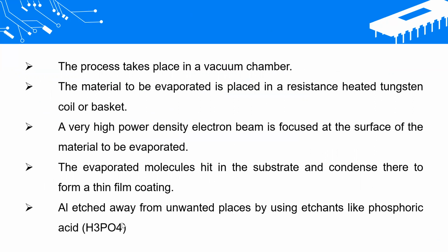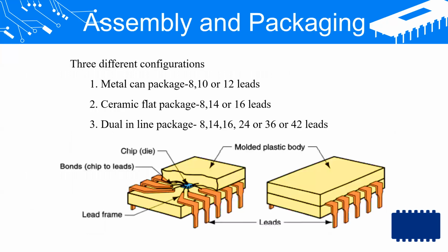Then after completing all the fabrication processes, several chips are ready on a wafer. Each of the chips is nothing but a complete circuit. Now, the next step is to separate out these chips and package them individually. Using a diamond-tipped tool, lines are scribed along the rectangular grid on the surface of the wafer. The wafer is cut along the lines drawn using the sharp diamond-tipped tool. Thus, individual chips are separated from each other.